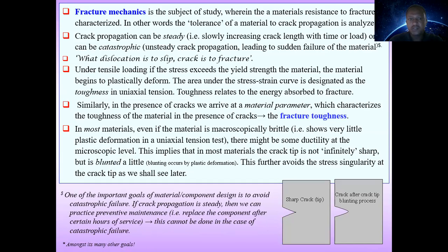Crack propagation can be steady, which means a slow increase in crack length with time or with load, or it can be catastrophic. That means unsteady crack propagation leading to a sudden failure of the material. So what dislocation is to slip, crack is to fracture.